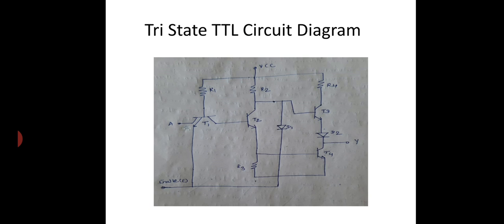It is called the Tri-State TTL because it allows three possible output states as high, low, and high impedance Z. In high impedance Z state, both the transistors in the totem pole arrangement are turned off so that the output terminal is a high impedance to ground or VCC, or the output is an open or floating terminal, that is neither low nor high.